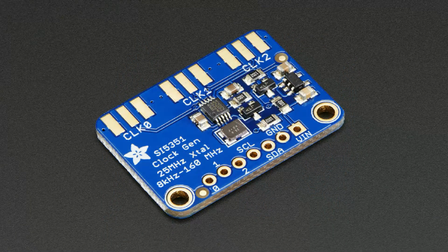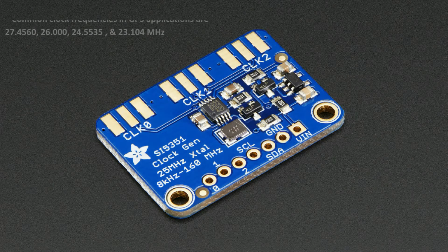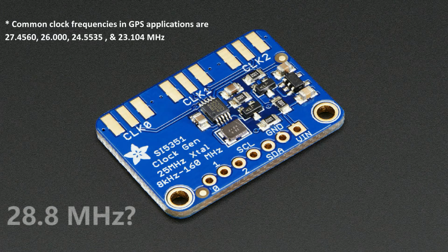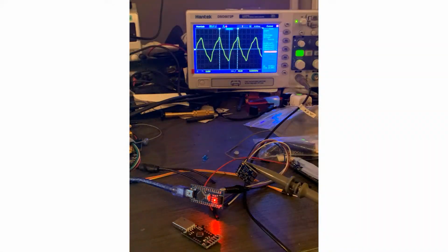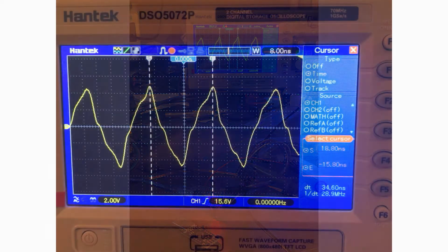Another solution we decided to explore was the development of a programmable external clock board that could be used to supply the four receivers. The clock of the SDRs uses an unconventional 28.8 MHz signal. We found a programmable board produced by Adafruit that could support this frequency.